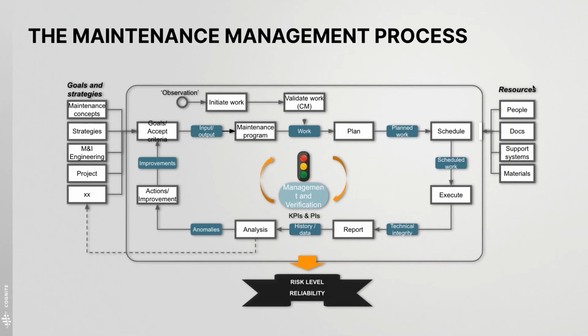Once these tasks and work packages are planned and scheduled, then comes the implementation. So the offshore technicians and service engineers responsible for the implementation print out the documentation, checklists, and permits. The area should be cleared and isolated if needed, in addition to reserving the material and tools needed for the job. During the shift change, also the technician has to document what has been covered in the last shift.